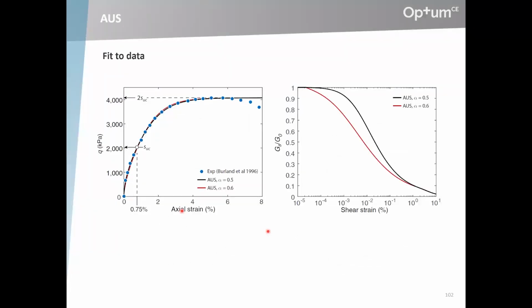So you can fit data really quite well. You're always sure to pass through the origin, of course, and then the halfway point, and then it levels off, so there's a limit to how wrong it can go. I should say as well that there is a final parameter, we call it alpha, in the vicinity of say 0.5 to 0.7, and it's meant to tune the behavior at very small strain.